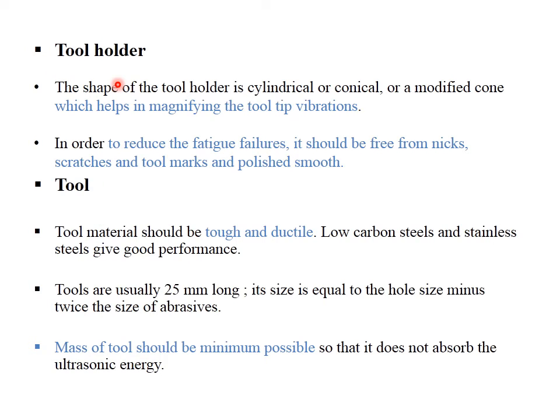So it has to be confirmed that whatever tool holder you use must be free from any crack. Because if there is a crack in a tool holder, then there is a chance of fatigue failure after a certain period of time.